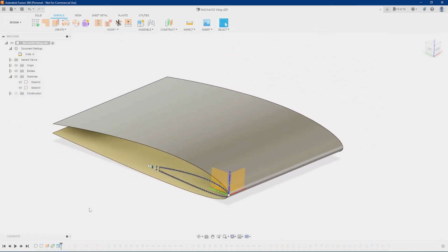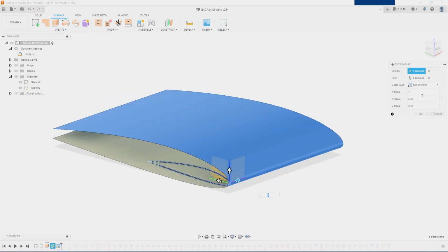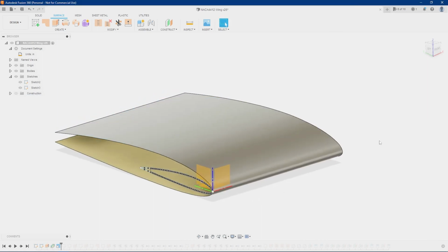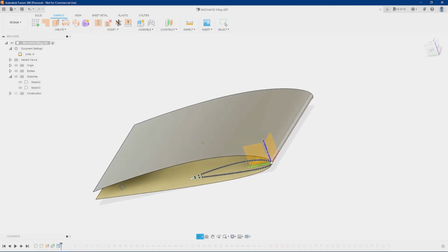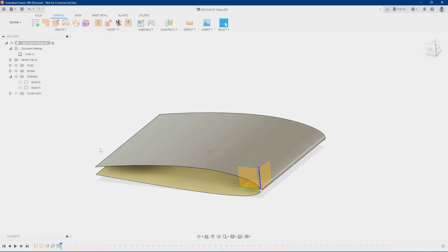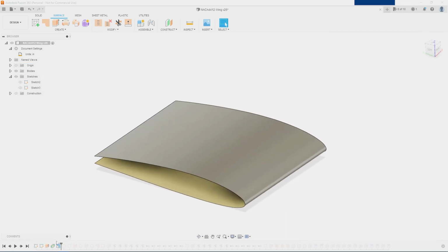And then you can see I scaled the Z and the Y here by 2.54 to essentially get back from centimeters to inches. I did that almost at the end of my CAD work and had to redo a lot of stuff. So if you're going to be recreating this and following along, definitely make sure that you set your scale properly.